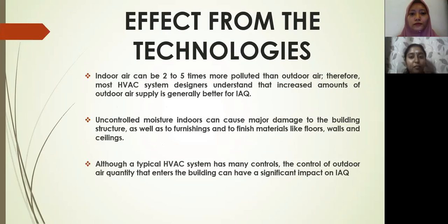For the effect from the technology, indoor air can be 2 to 5 times more polluted than outdoor air. Therefore, most HVAC system designers understand that an increased amount of outdoor supply is generally better for IAQ. Uncontrolled moisture indoors can cause major damage to the building structure, as well as to furnishings and finished materials like floors, walls, and ceilings. Although a typical HVAC system has many controls, the control of outdoor air quantity that enters the building can have a significant impact on IAQ.